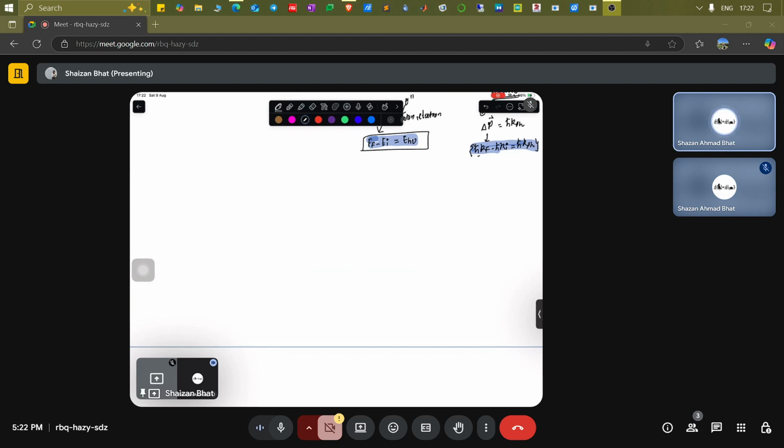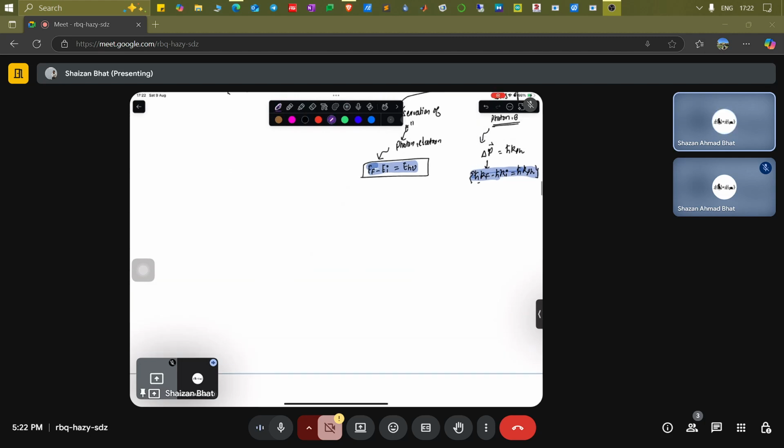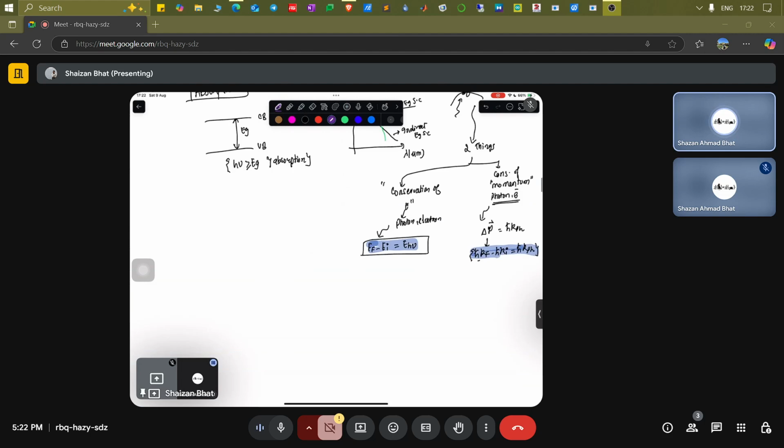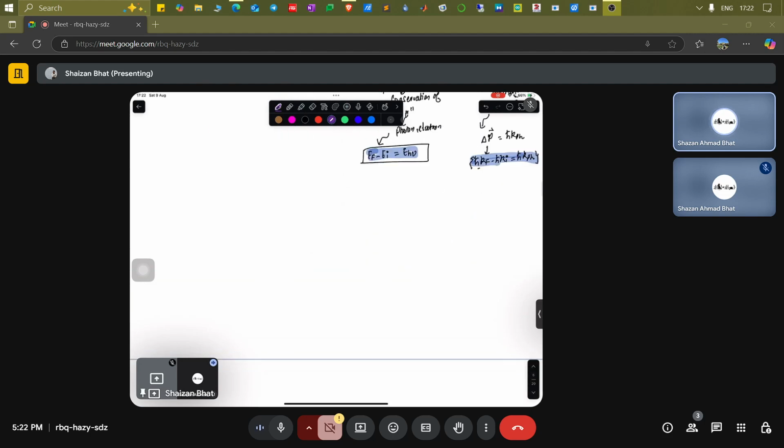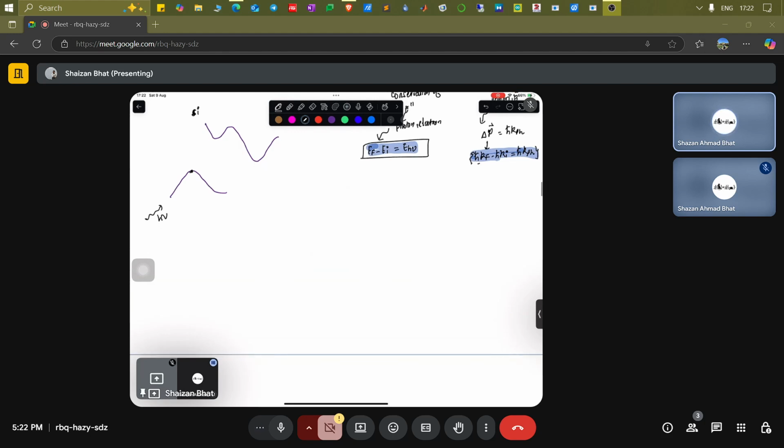So that is why the absorption is bad there. The absorption is not good, and also there are different processes in indirect band gap semiconductors which compete. Let's say, for example, if you talk about silicon, if the photon comes in, then you know that the photon doesn't have enough momentum to take the electron in this direction. It's not going to go in this direction.